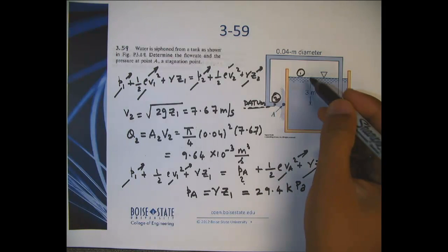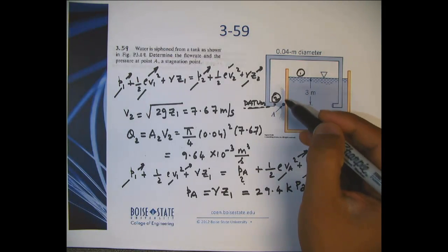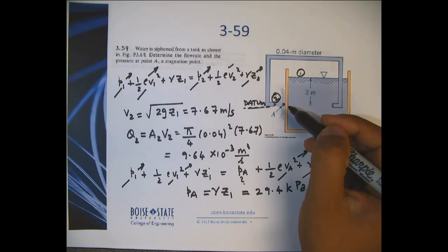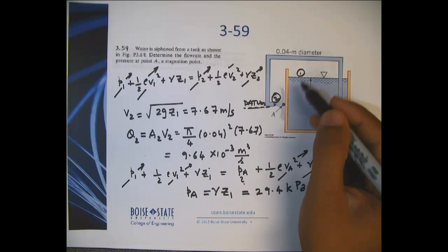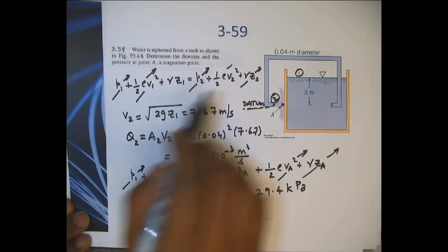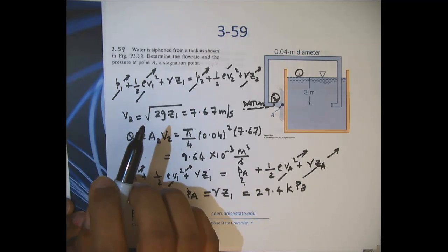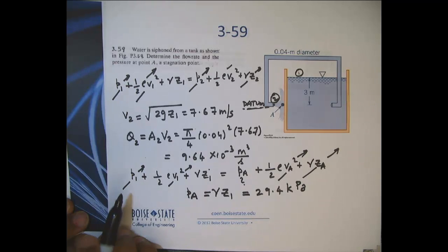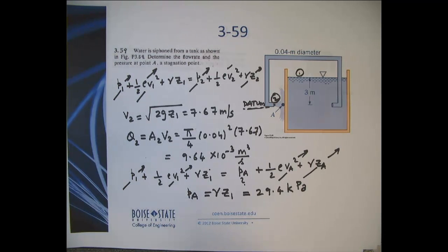Okay. You see that Bernoulli equation and the mass conservation are so easy to apply. It's just that I want to know what things you want to find out and then make sure you have a streamline and apply the Bernoulli equation along that streamline between those 2 points. And make sure when you apply, you end up with one equation and only one unknown. Otherwise, you might have to use something else, like in conjunction with Q2 here, which we did. Okay?